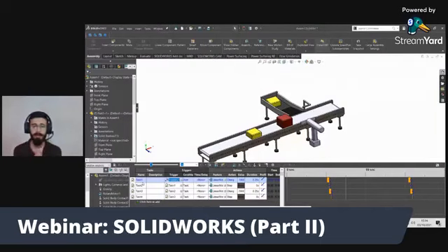The first command: the proximity sensor is the trigger. What's the first task my sensor is doing? It is alerting my actuator that now you have to move. My actuator moves, and in the next task my actuator stops at a certain limit, then in the third task the actuator goes back, and the fourth task is the actuator stopping at its initial position.